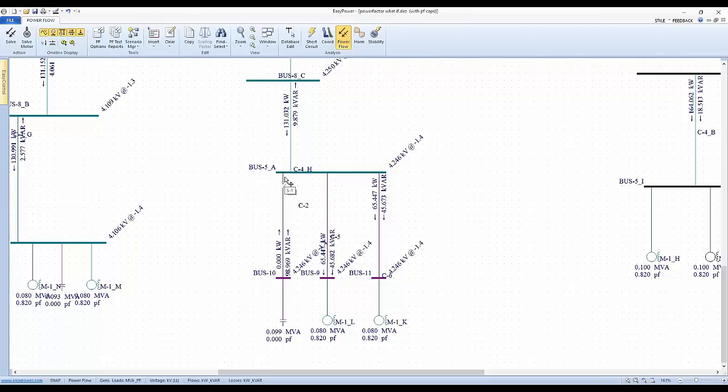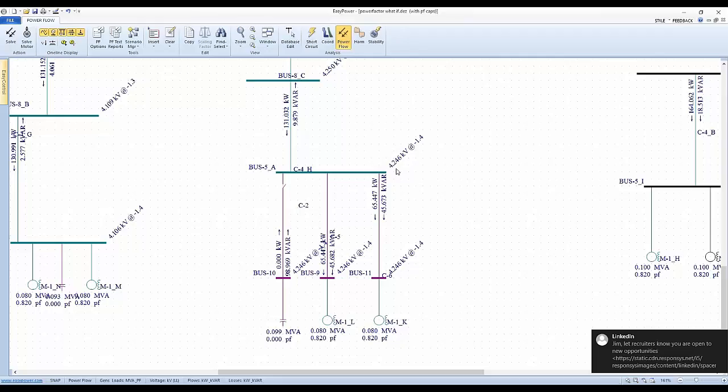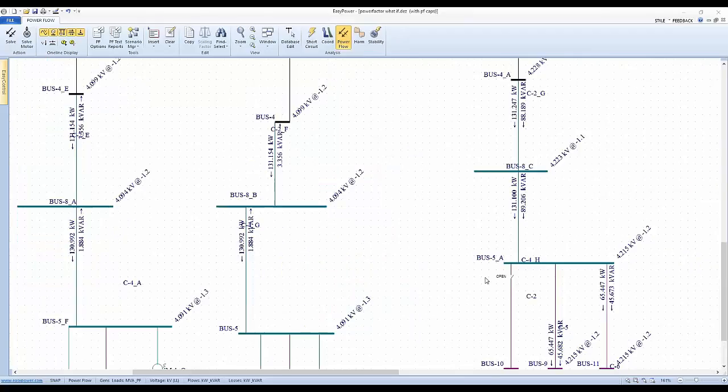capacitors rather than being a burden both in efficiency to our system, but as a power factor demand on the utility. The other interesting thing, and the other reason for having a capacitor in line, and another reason we might want to maybe bring these values down a little bit, is that now that we've eliminated this loss that's going to be in the cable and the transformers, we've actually brought the voltage up, and so our motors are going to be more efficient just in their normal operation.